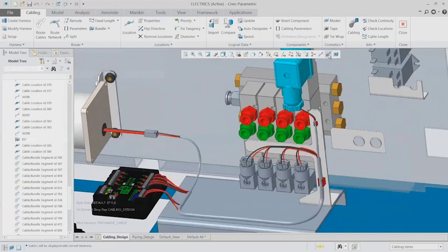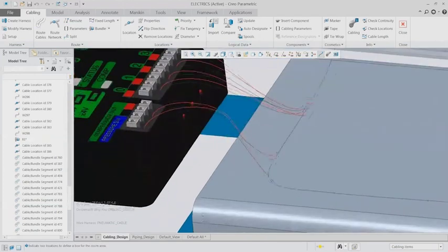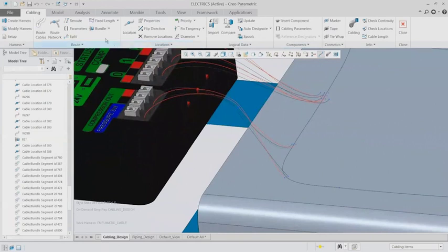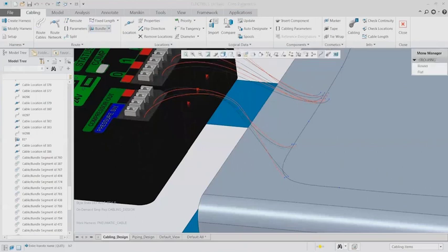And that's going to even clean up that simplified representation of the model as well. It's just going to be one unified line encompassing all the different cables I have. Now I can always go back and modify those bundles at any point or add things like different types of branches. So here, we're going to create a new bundle, and this is just going to be something that branches into another harness. So it's not going to be its own fresh one. It's going to be a branch.